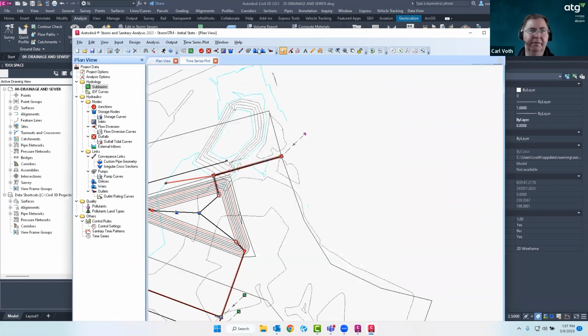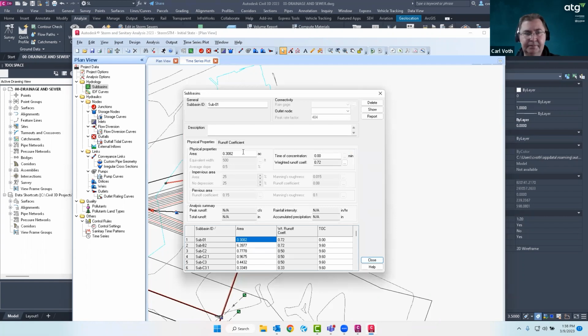We could come through and add these subbasins in manually. And if you've noticed, let's draw those in. If we wanted to trace an area, we can do that. And then we have our catch basin there. We come back and then edit that catch basin. So what it's being traced at is 0.3 acres. Now it's actually 6.32. And give it our time manually if we need to.